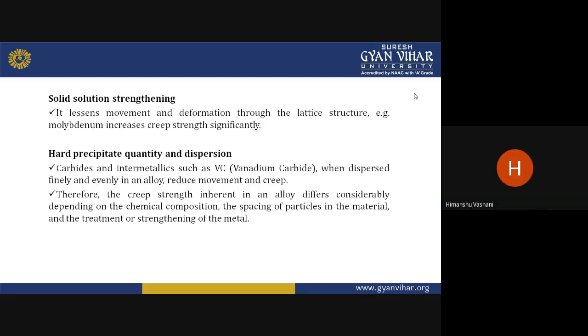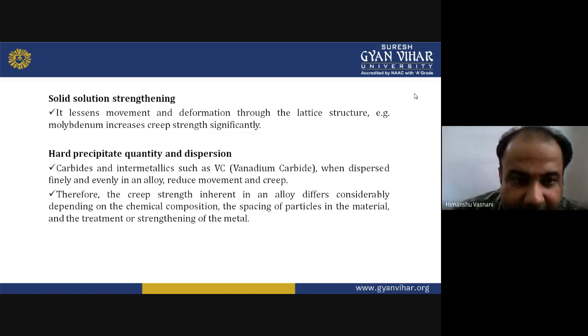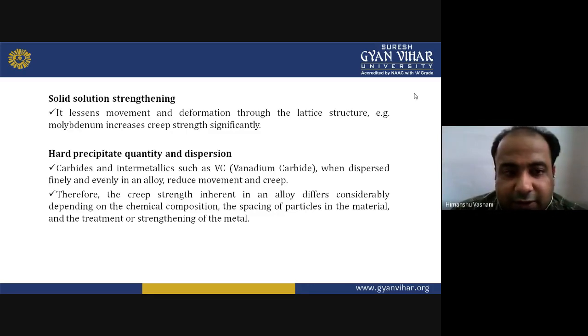Now, solid solution strengthening lessens movement and deformation through the lattice structure. For example, molybdenum increases creep strength significantly. Then, hard precipitate quantity and dispersion, like carbides.